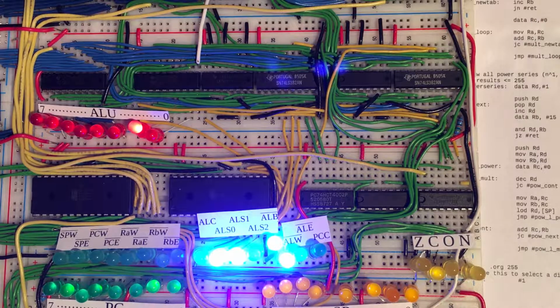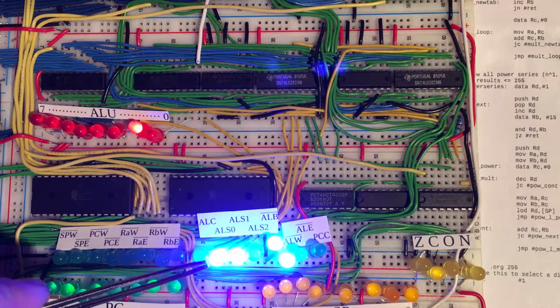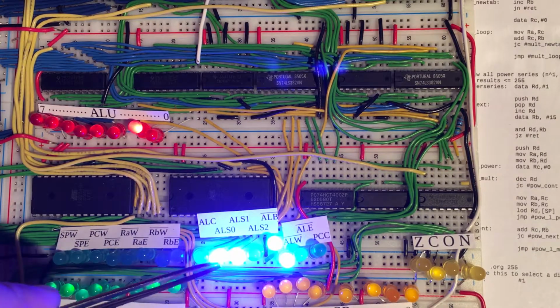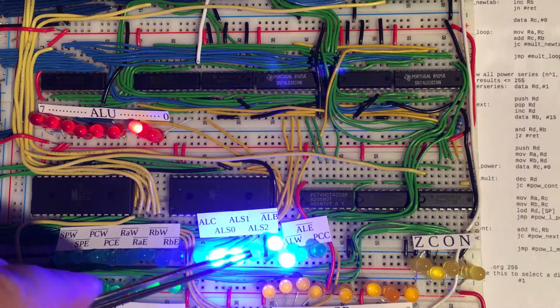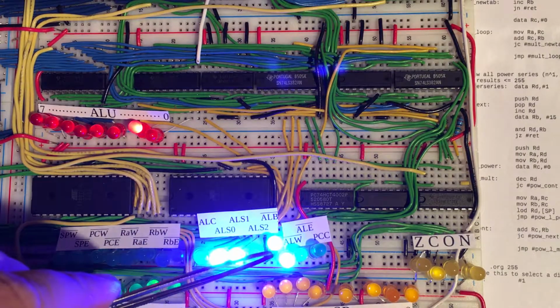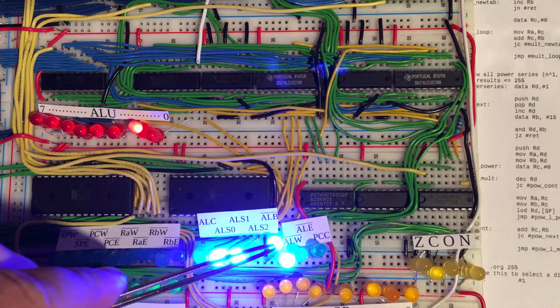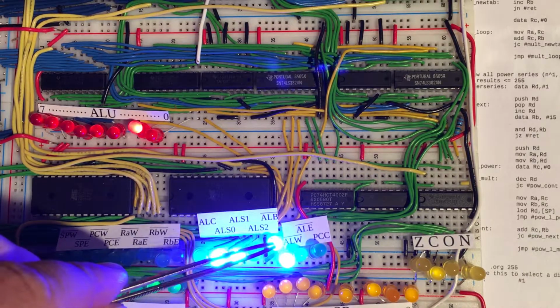And at this moment the C register contains a value of 28 and the B register contains a value of 7. So that 28 is being output onto the bus and is coming into the ALU along these wires and is going into the first operand. And so the control logic is once again giving this 4-bit signal to the ALU, which in this case means an add. But for this add, it's actually going to take the contents of the B register, so it's not an increase or a stack instruction.